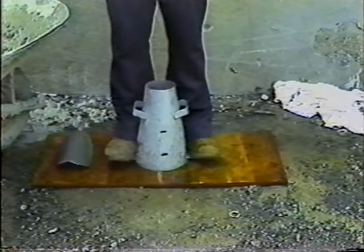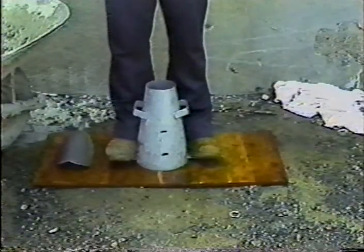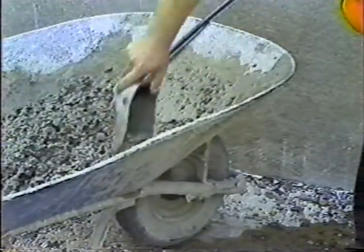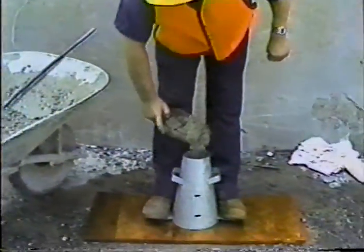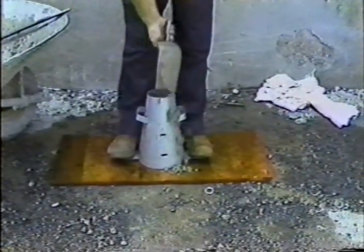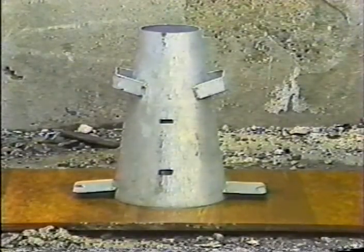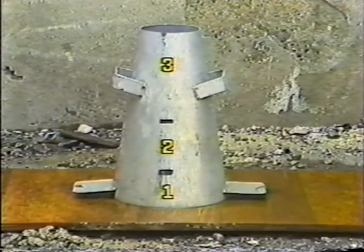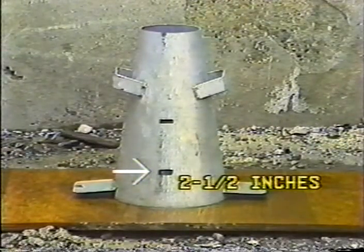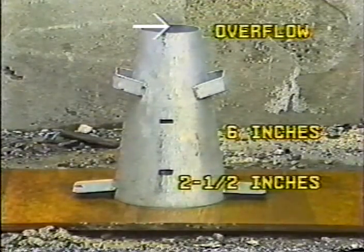The person doing the test should step onto the footholds at the bottom to hold the cone steady and stay there. That's why the cone should be close to the concrete sample. Now we can start filling the cone. It's best to move the scoop around the top to get the concrete distributed as evenly as possible. The cone is filled and rodded in 3 layers by volume, not according to the height of the cone. The first layer should come up about 2.5 inches. The second layer should come up about 6 inches, about halfway up the cone. And the third layer should overflow.